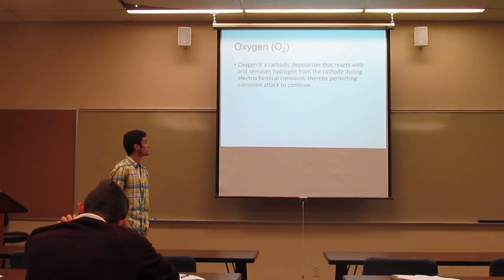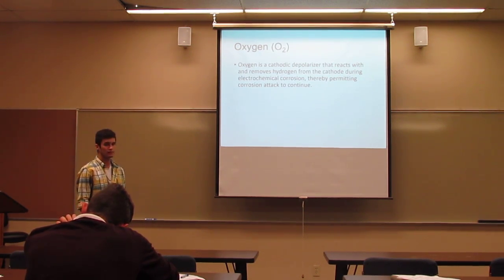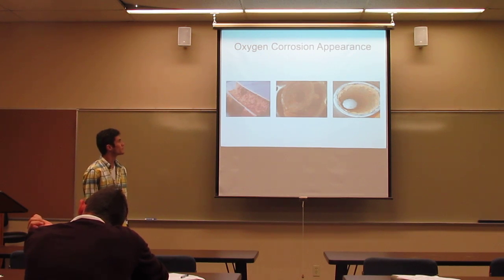Next one's going to be oxygen. Oxygen is a cathodic depolarizer that reacts with and removes hydrogen from the cathode during electrochemical corrosion, thereby permitting corrosion attack to continue. Here's some pictures.